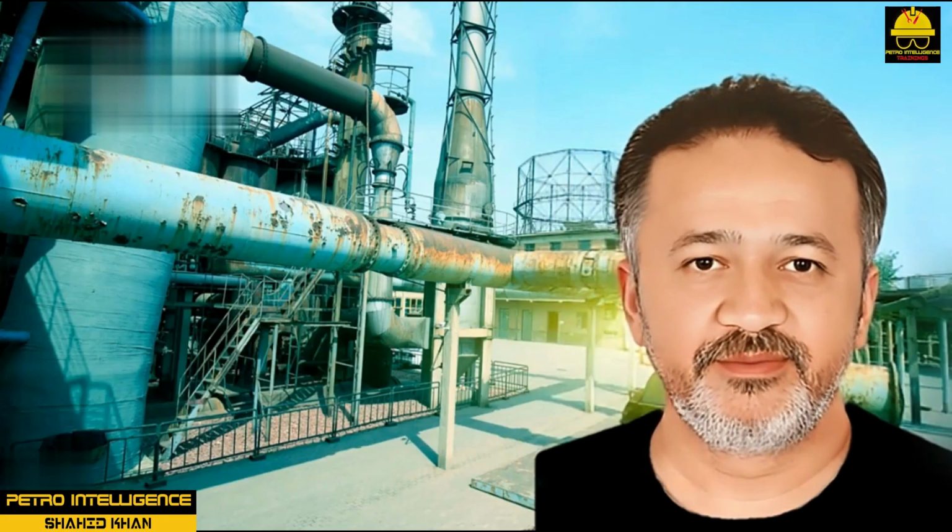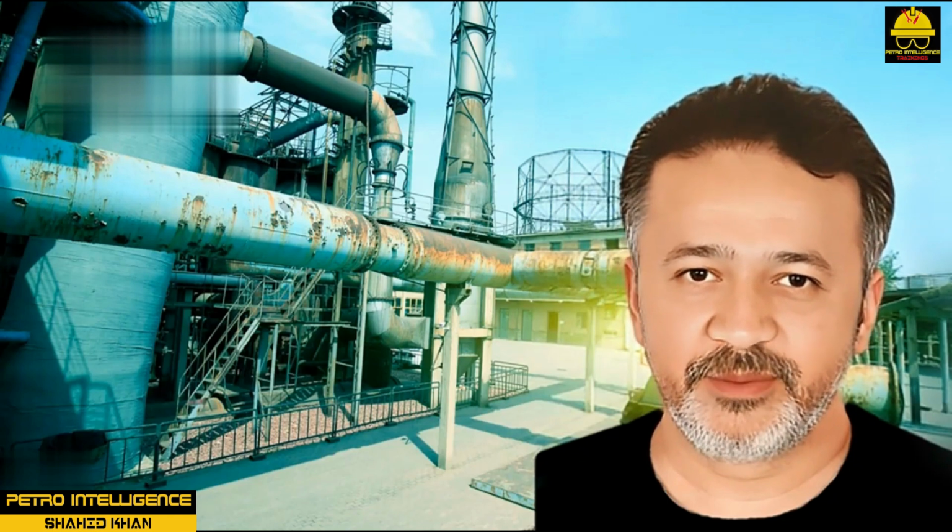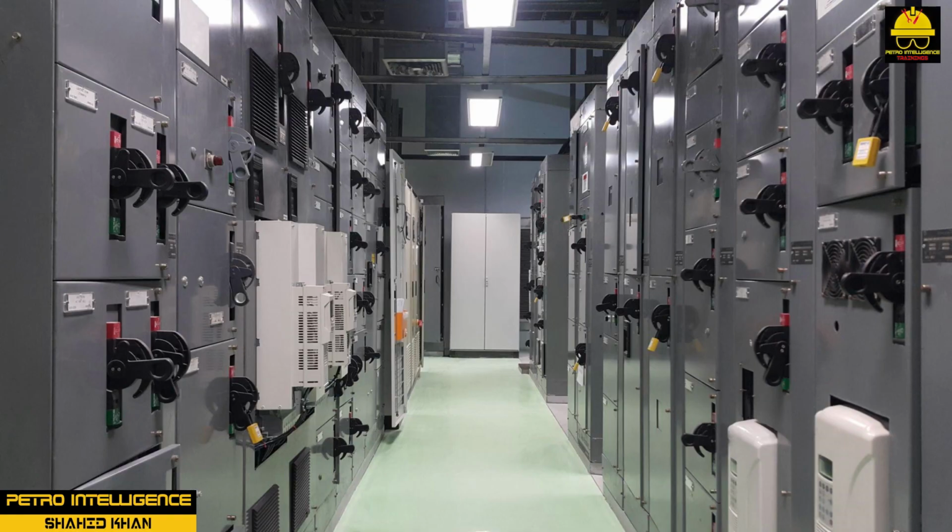Electrical systems. The power received from electric supply companies is generally at voltage levels of 100 to 160 kV. At many plants, this is transformed down to 13.8 kV for distribution within the plant. At the units, the 13.8 kV is stepped down to 4,160 V for use on large motors, 200 to 10,000 horsepower. The 13.8 kV is also transformed to 480 V, the most common voltage in many plants, and finally to 240 V and 120 V for heating, lighting, and fractional horsepower motors.